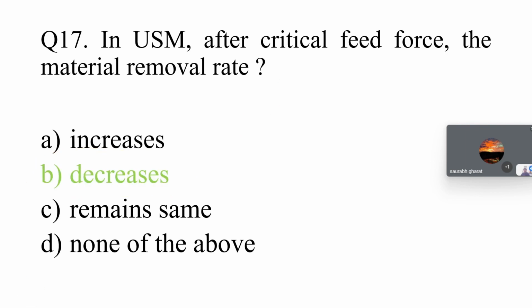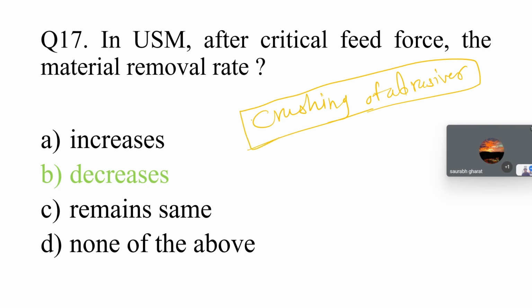After the critical force point, many factors will accumulate there, due to which crushing of the abrasives will happen. So due to this, the material removal rate will decrease. This decrease will be your answer over here.